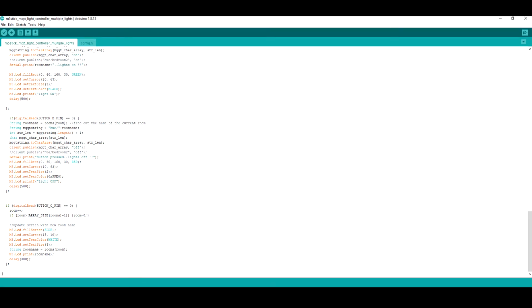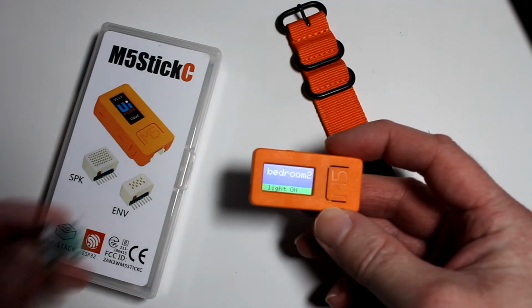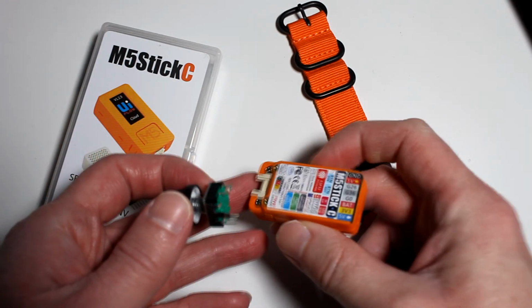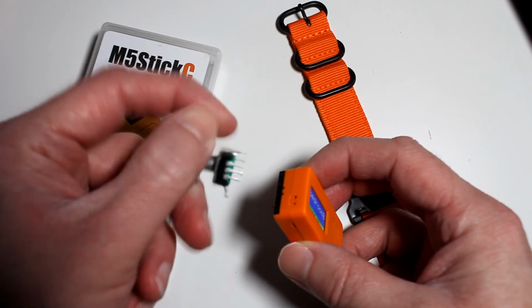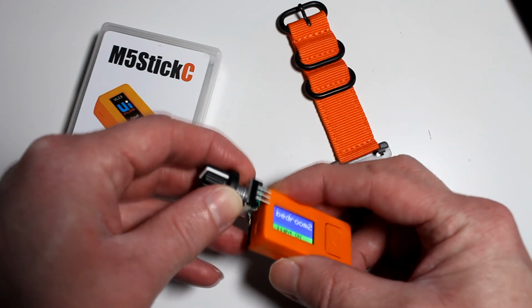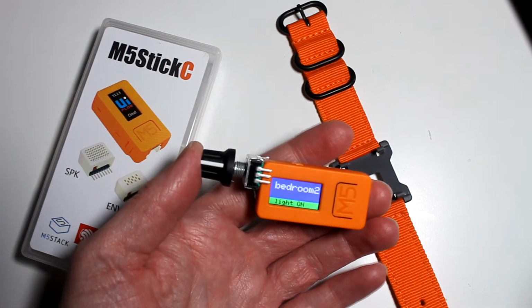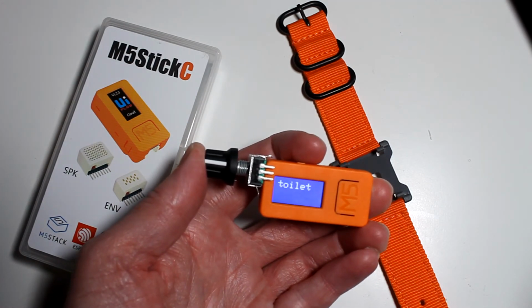Now to make it work, you just need to upload it to an M5Stick. And you need to add a switch at the side. I'm using the push button on a rotary encoder simply because the pin spacing is ideal, but it also looks slightly steampunk. The actual encoder pins are not used here. You could actually modify the code to change rooms by turning the encoder instead of pushing the button. And my last video on ESP32 did include the code you need to use an encoder in ESP32. So if you are interested in doing that, go and watch that video.